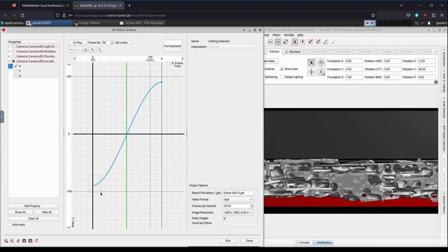Now we will select the first control point and adjust the first slope value to 2. The first slope value affects the values coming from the selected control point. Then we will move on to the second slope value, which influences the interpolation that ends at the next point. We will change the value also to 2.